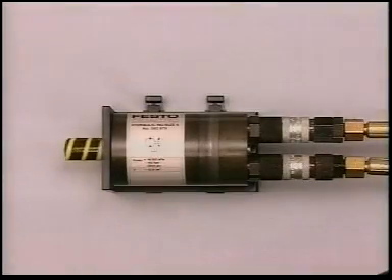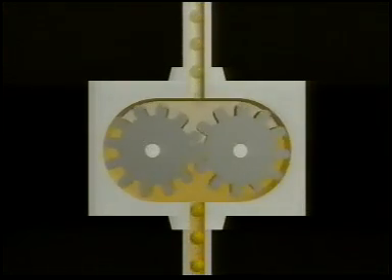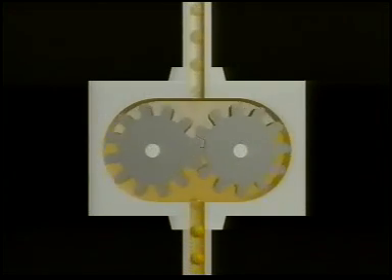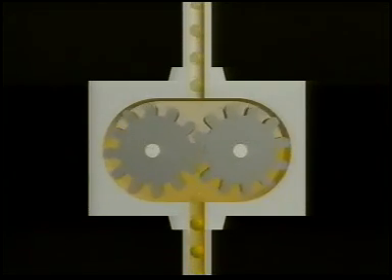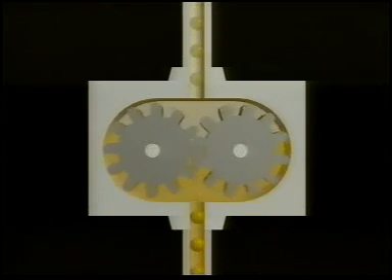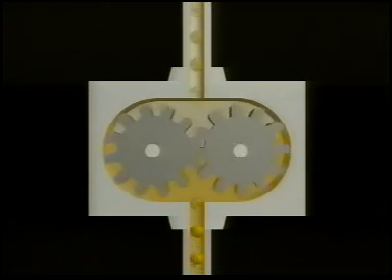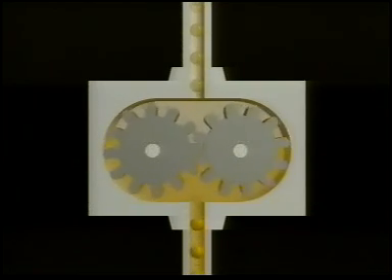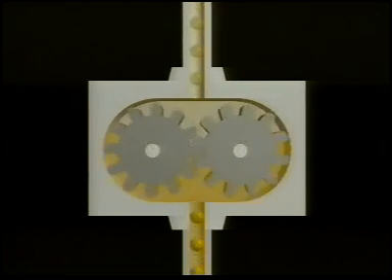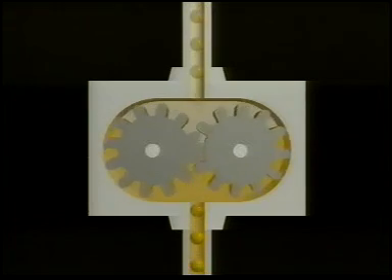And now to hydraulic motors. Basically, they function just like hydraulic pumps, only the other way around. The hydraulic oil, which is under pressure, drives two intermeshing gear wheels. It flows along the chamber wall and becomes almost unpressurized because it only has to overcome line resistance as far as the oil reservoir. An important characteristic of hydraulic motors is the consumed volume V.